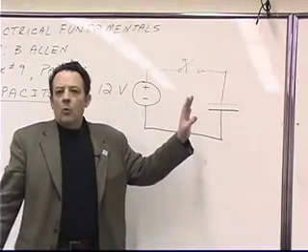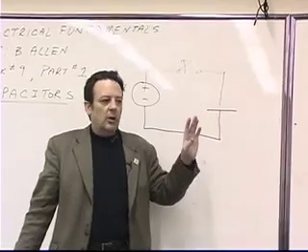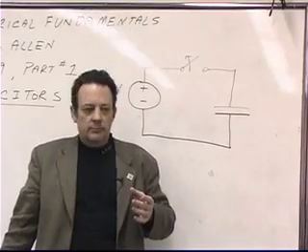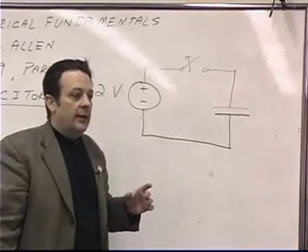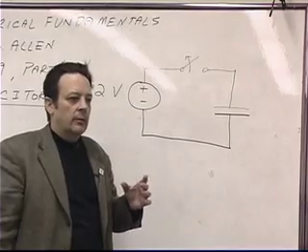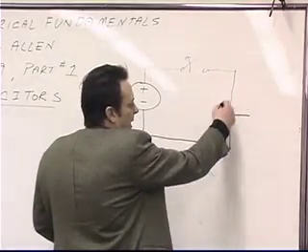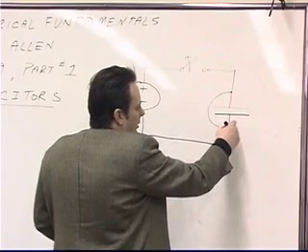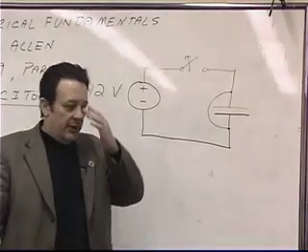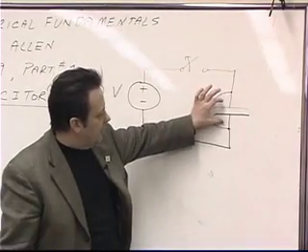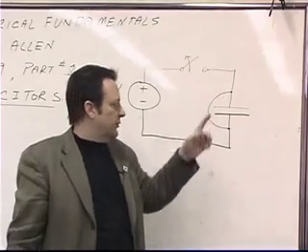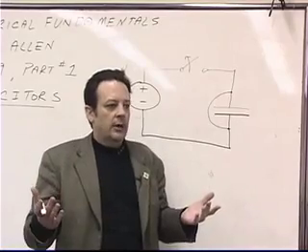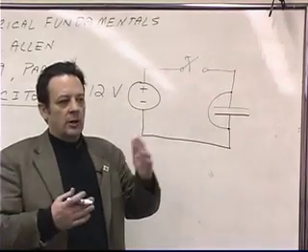Now, when we buy these things from a supplier, okay, they come in what we call a neutral configuration, meaning that the two plates were at some point in time shorted out. And so generally when they manufacture these capacitors, they'll just take one lead and they'll just short to the other lead. And what that does is it causes both of these plates to be at the same voltage. Because if there's a short right here, right, then they're effectively at the same node. Okay, so there won't be a buildup of charge on either the top or the bottom.